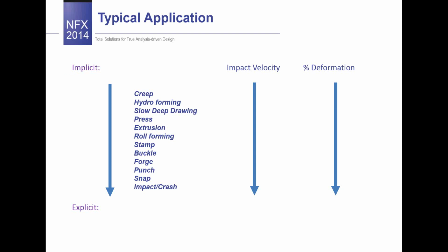A high degree of material nonlinearity may require a small time step for accuracy when you want to perform calculations with large geometric nonlinearities. Some contact and friction algorithms can introduce potential instabilities, and a small time step will be needed for accuracy and stability, and so on.